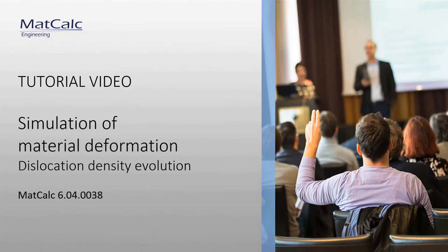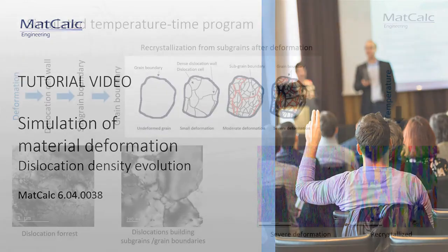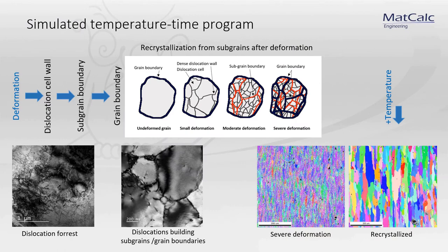Such simulations can help us, not only to understand the phenomena behind thermomechanical processes, but also can quantify material changes during processes. During deformation, the dislocation density in the system increases, resulting in diffusion enhancement. Furthermore, the dislocations may orient themselves to subgrains and during the subsequent healing process transform into new grains and recrystallization.